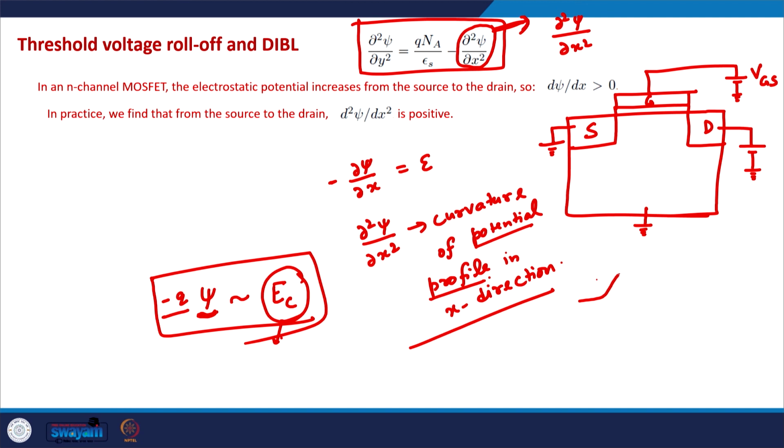So, this is how the barrier actually looks like in the semiconductor when we apply a certain drain voltage. This is the top of the barrier, this is where we think that the source is located. This is also known as the virtual source point of the device, because this is the point where the gradient of the band is 0, which means that the electric field is 0.